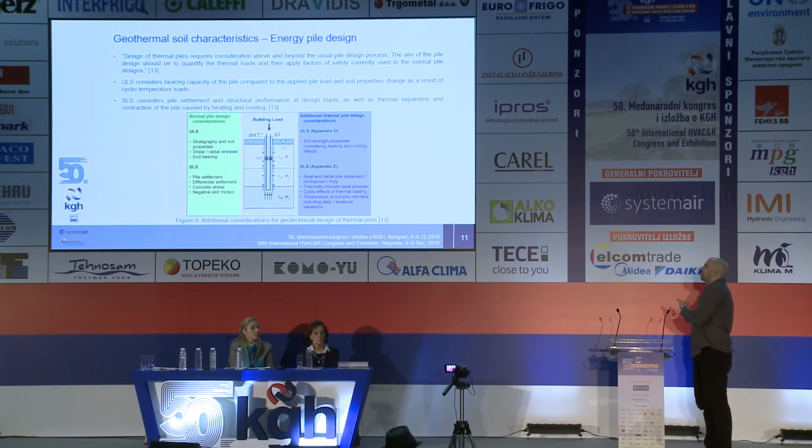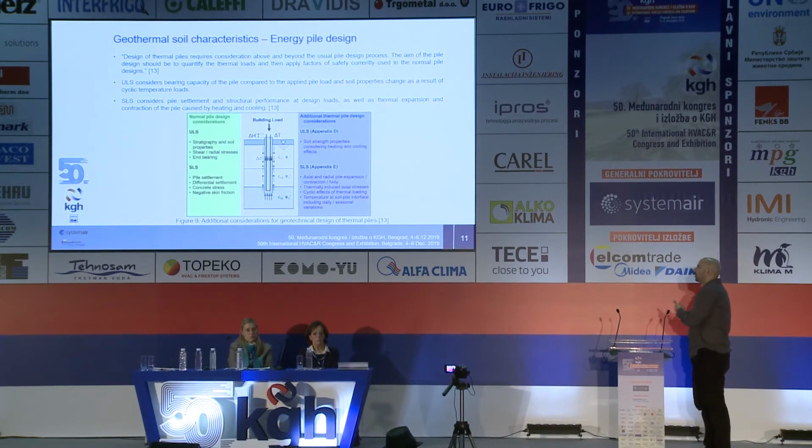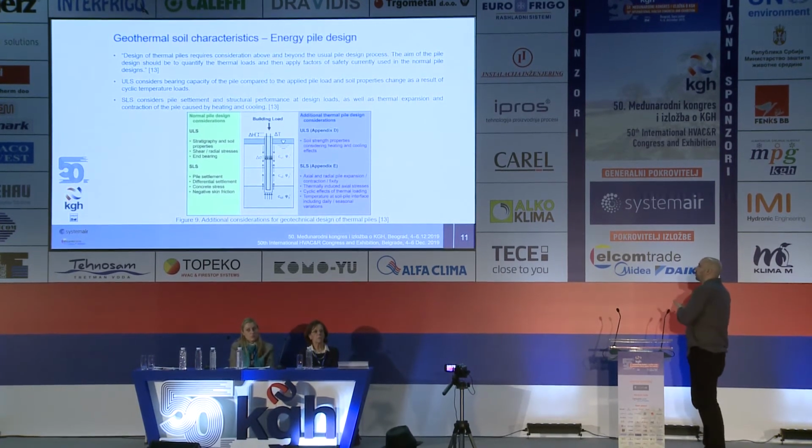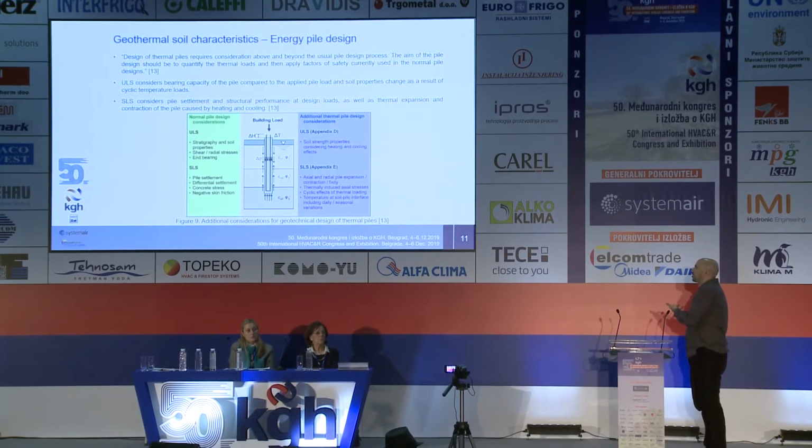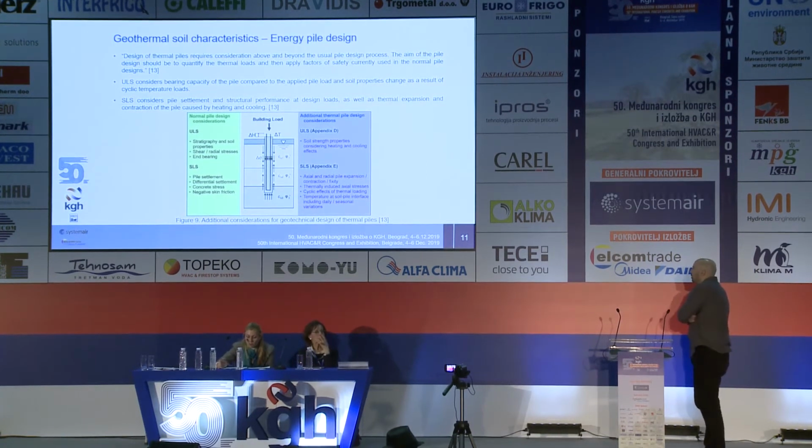We have some regular consideration when we analyze regular or conventional piles, but when it comes to energy piles, we also need to consider some other aspects, like, for example, at ULS, we need to consider the bearing capacity of the pile compared to the applied pile load, and soil properties change as a result of cyclic temperature load. So basically we need to incorporate in our calculations the cyclic temperature change.